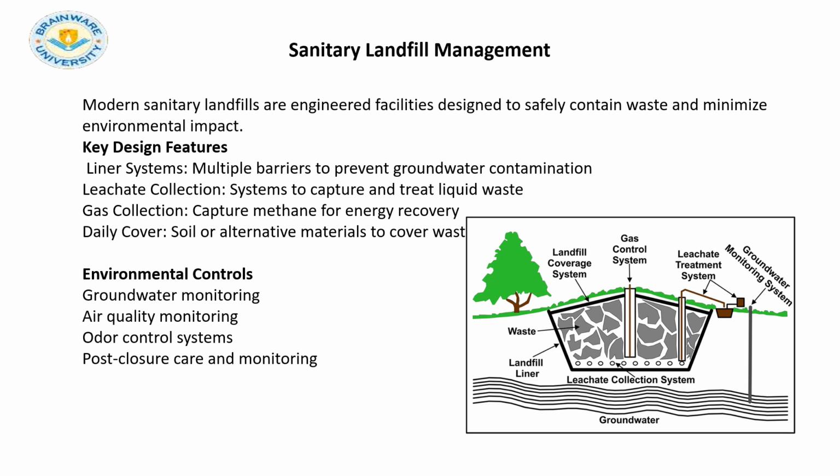There is another chamber which we call the gas collection chamber. Since landfill management is an anaerobic process, from the solid waste we capture methane, and that can be used as a renewable source of energy. And for the daily cover, we can use soil or alternative novel materials in order to cover the waste.